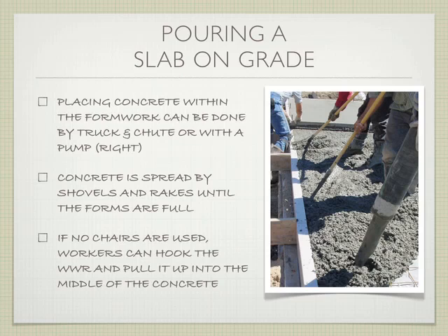If you're not using chairs, this is the thing I talked about before, you can reach through the concrete, because remember it is a slurry, and you can pull up that welded wire reinforcing up into the slab so that the concrete oozes around underneath it. Which is acceptable, though it's not as accurate as if you had chairs. If you put the chairs in, the reinforcing is right where it should be, at, say, 2 inches above the bottom of the slab. If you just reach in and pull it up, maybe it's 3 inches, maybe it's 1 inch. You don't really know. But it's another method that is commonly used.